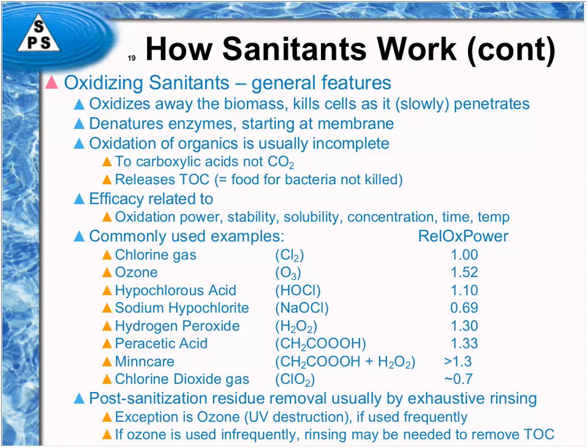And if ozone is used on an infrequent basis, then you may have actually released a lot of TOC into the water that needs to be rinsed out. So don't think that ozone always can be destroyed or should be destroyed just by UV destruction. You may find that there are many advantages to rinsing out a very infrequently sanitized ozonated system.